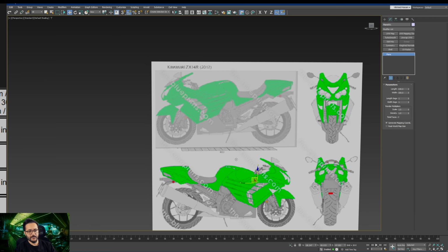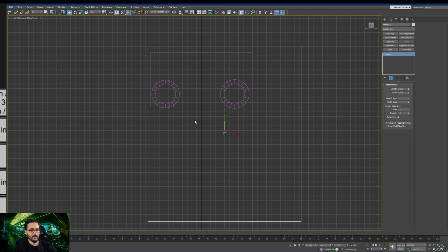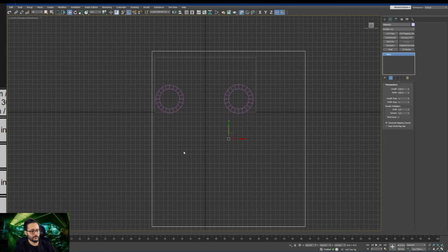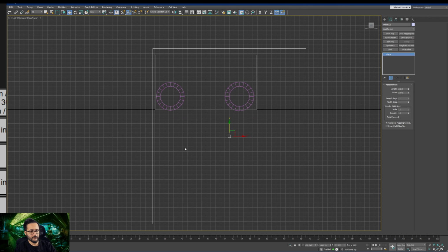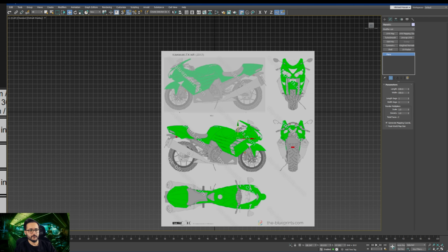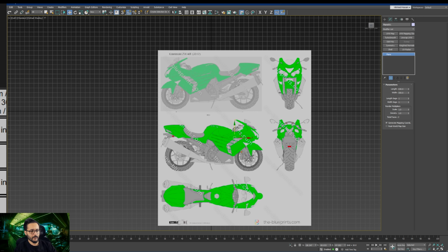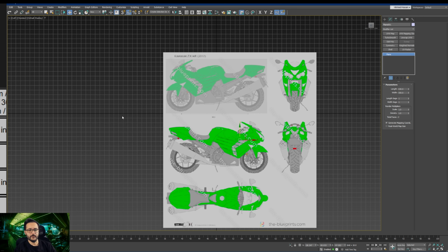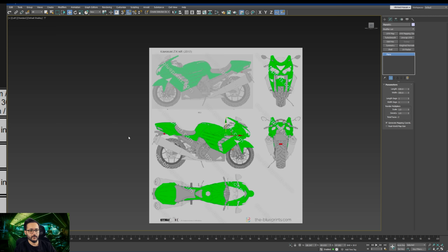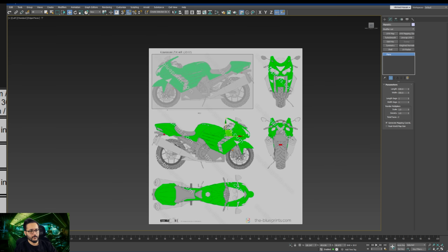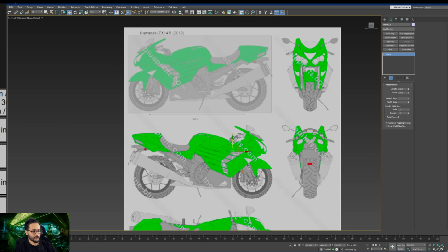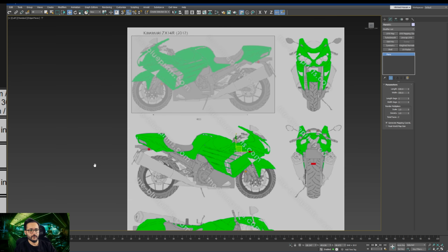You can press L on the keyboard to go to left side, and you will see this. You can press F3 on the keyboard to toggle between the wireframe and the solid color, default shading. We don't need the grid now. To hide the grid, press G on the keyboard. The grid is gone. So we can show the wireframe so the box is a little bit more visible. We can press F4 on the keyboard.